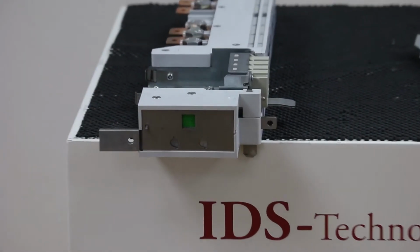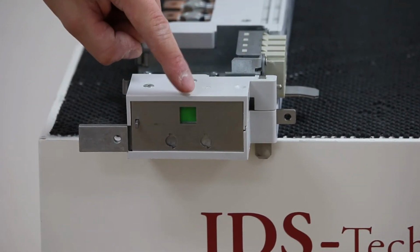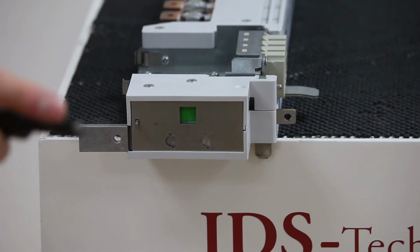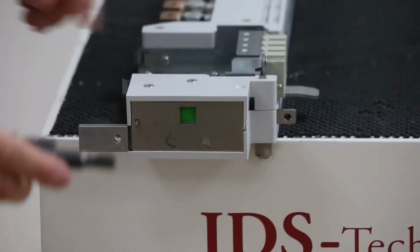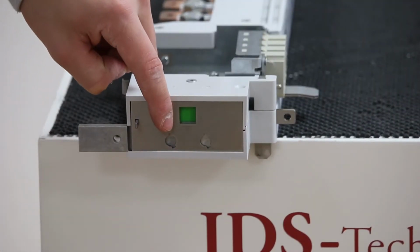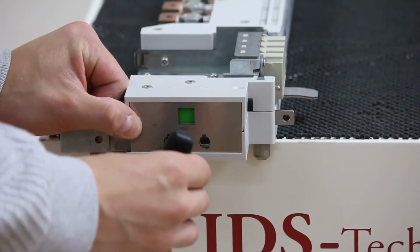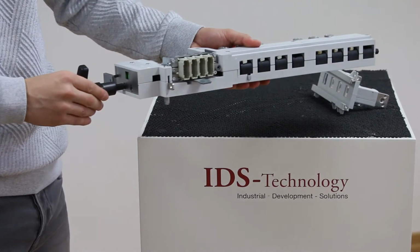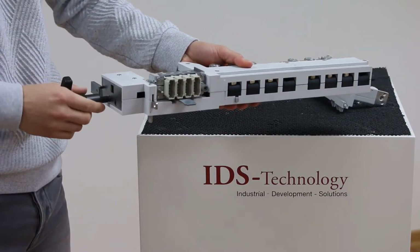To move to test position, starting at disconnected position, showing label green, insert the operating key with its nose at 12 o'clock into the hole at left. Push the key and turn right until reaching the end position.